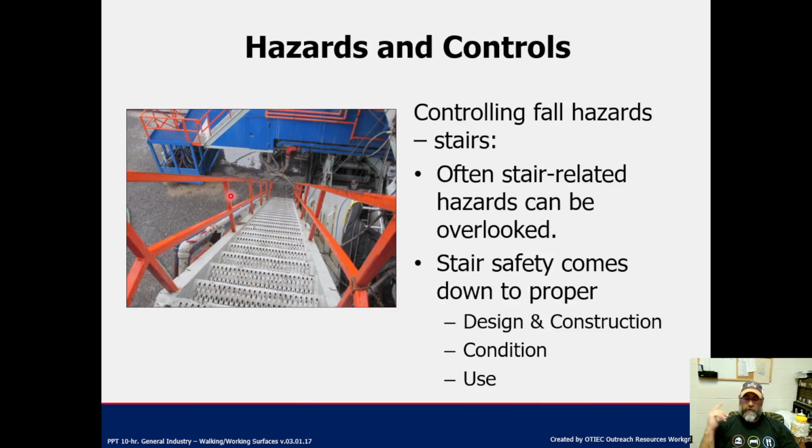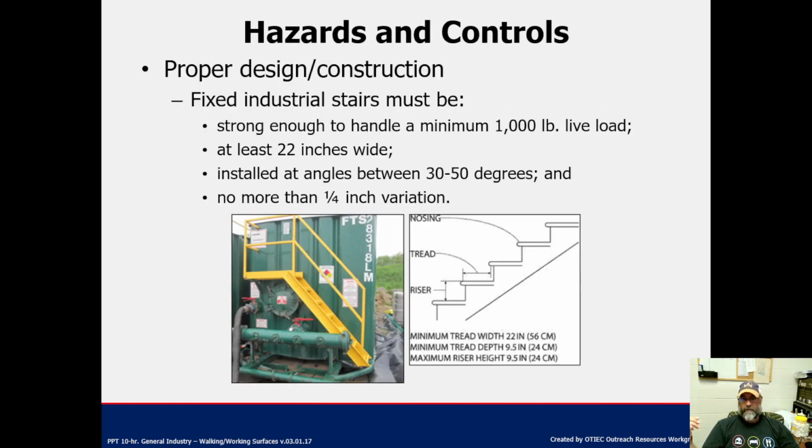All right, using stairs safely. Industrial facilities need to maintain a 1,000-pound live load. Most of the stairs you're going to see are steel, 22 inches wide. You know, you can't have them too steep. Those of you who've been on a Navy ship, I think those things are a little bit more than 50 degrees, but more like ladders. But they have to be at a safe angle. You cannot have some sort of extreme angle to try to access equipment.